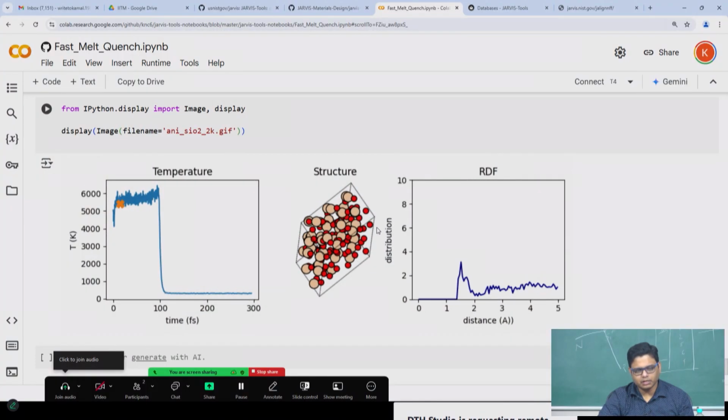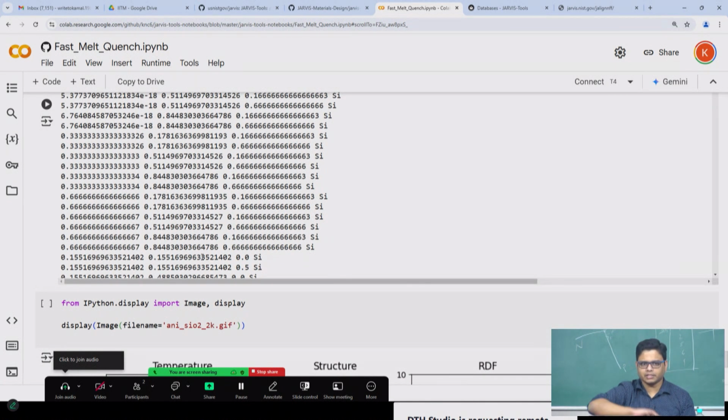So earlier force fields could not keep the temperature almost constant. It was crazy varying. When your force error is very high, you won't be able to conserve the temperature, and that's one way to test whether your force field has reasonable forces or not. So just do this with NVT. Do a melt quench of silicon. You will know whether it's a good force field or not. Silicon oxide, aluminum oxide, you just run the same or a similar script, and you'll have some idea about the quality. And of course, you can do vacancy formation energy, lattice constant, and stuff like this, which is a part of CHIPS-FF.